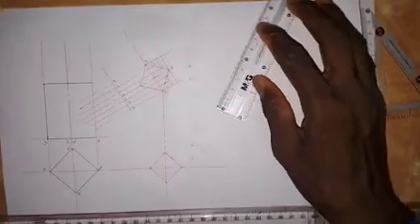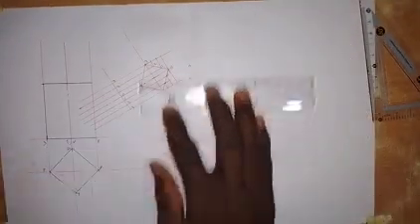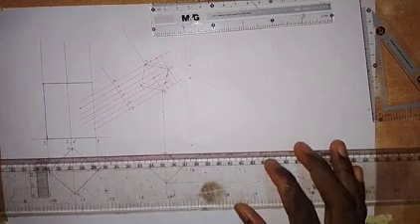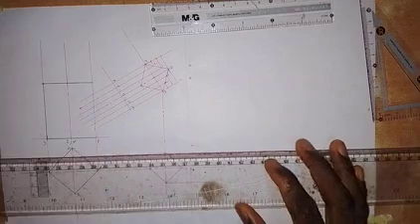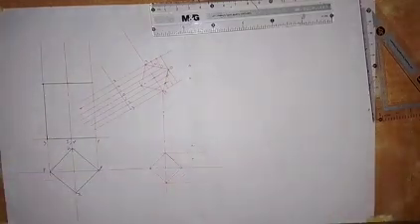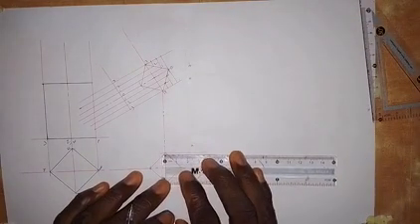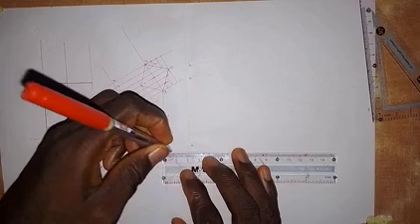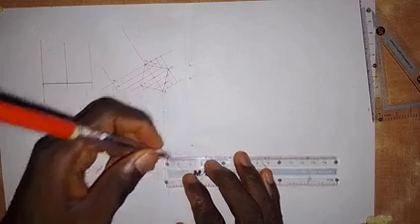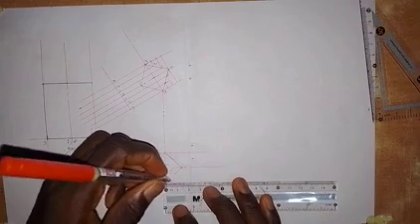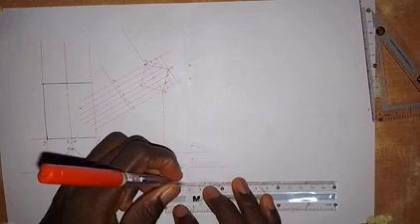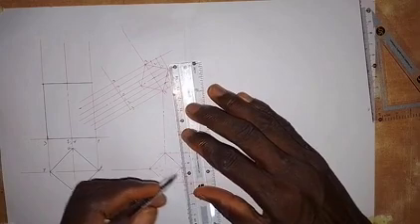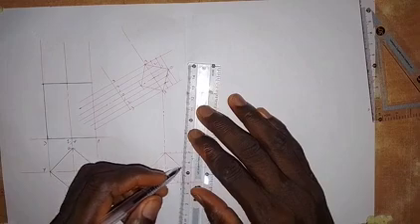So also I'm going to divide this into a number of equal parts, that is into 3 parts as we have done up there. So we divide this side and this side into equal parts. To do that, I'll just take 5 millimeters as I did for the one up there. So this is 5, 1, 2, 3, and this is also 1, 2, and 3. Okay, so join the last one to this end. Then I will join this to this end.